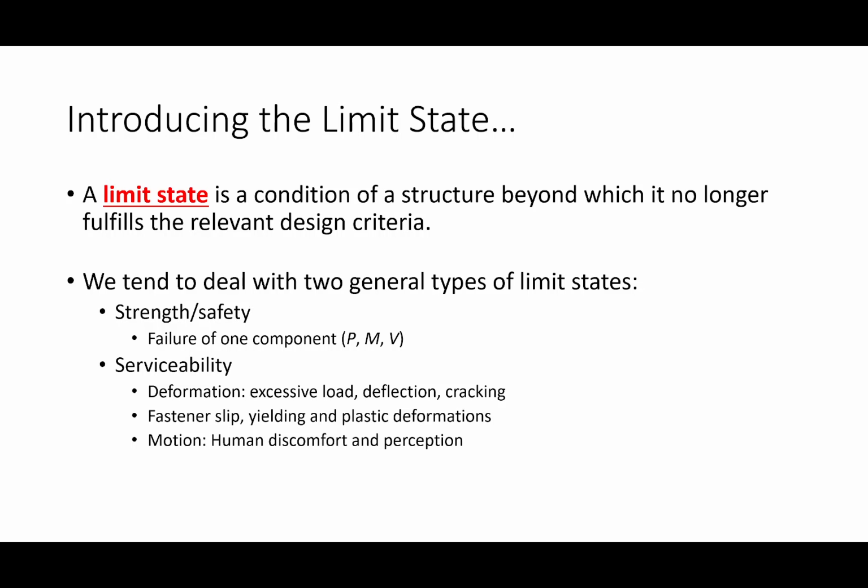Now, does that mean there's going to be a few beams in the building that are over-designed? Yeah, it is, okay? But is that going to mean a faster and more optimal construction process? Yes, okay? Not only is the frame going to affect the cost, but the construction as well, okay? And so there might be systems that you use that might not make sense from a weight standpoint, but it might save you labor. It might save you time, okay? So I just throw that out there as a nugget to think about.